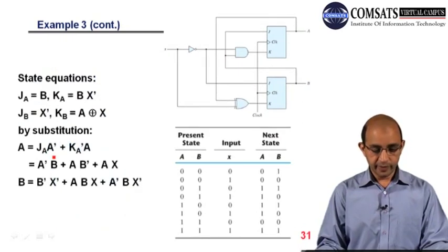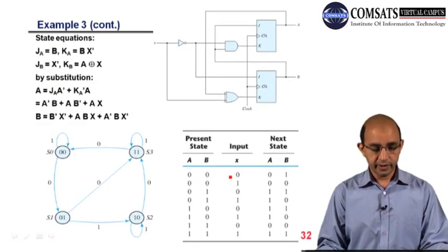So if you go back, here we can say that these are the possible combinations. Possible combinations are somewhat different from the number of states. You have to be very careful whenever we talk about the states and the possible combinations. Then we have to draw the state diagram if I have the state table. This is the state table mentioning the present state, input, and the next state.